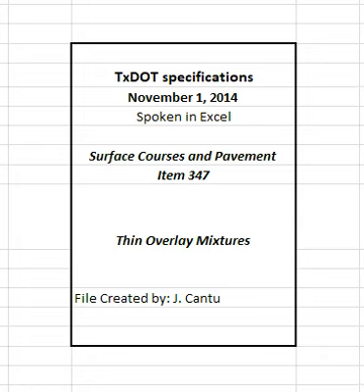When WMA is required, the maximum placement or target discharge temperature for WMA will be set at a value below 275 degrees Fahrenheit. Department-approved WMA additives may be used to facilitate mixing and compaction of HMA produced at target discharge temperatures greater than 275 degrees Fahrenheit, however, such mixtures will not be defined as WMA. 2.7 Recycled materials. Recycled materials are not allowed for use. 3. Equipment. Provide required or necessary equipment in accordance with Item 320, Equipment for Asphalt Concrete Pavement.